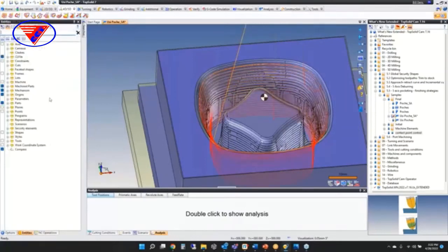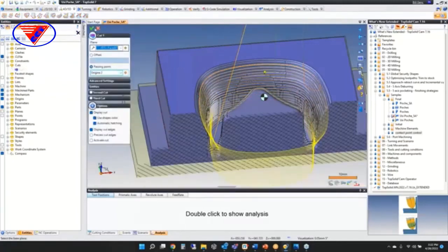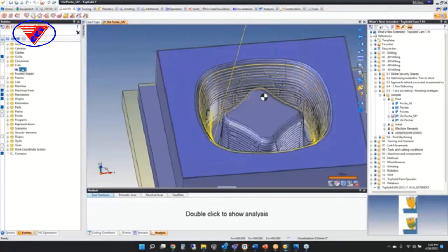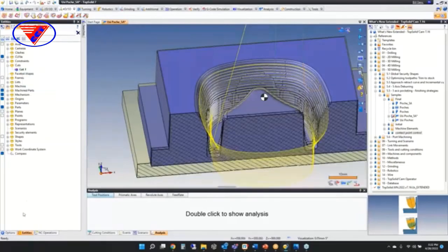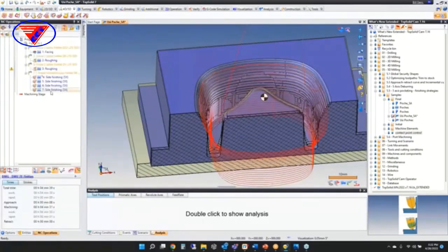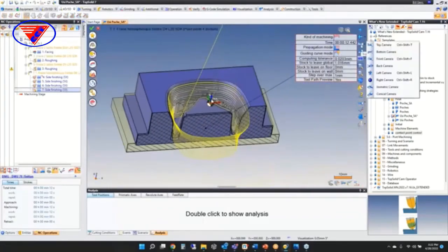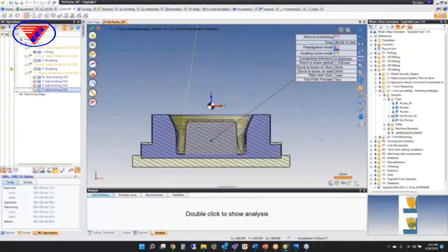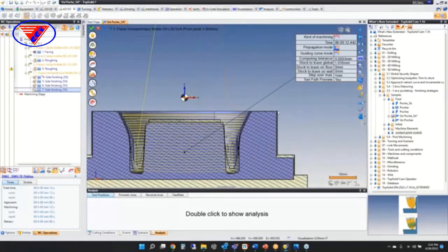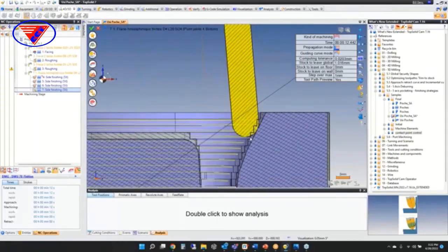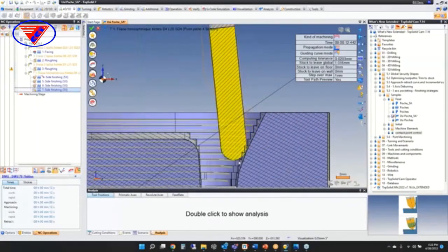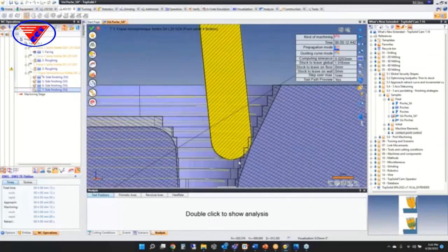And if I go activate that cut that I had up before, lovely. Activate. And we go back and edit this operation. And let's go look at this right on from the front, shall we? Put our tool on. You can see, as I drag down the tool here, it's staying at that 85% of the side of the cutter. Okay.